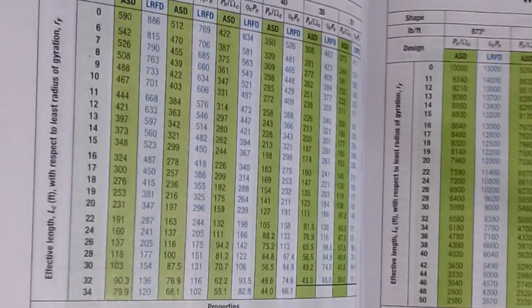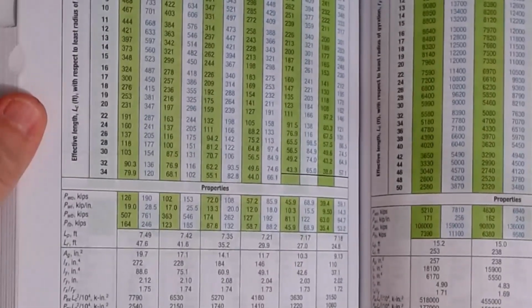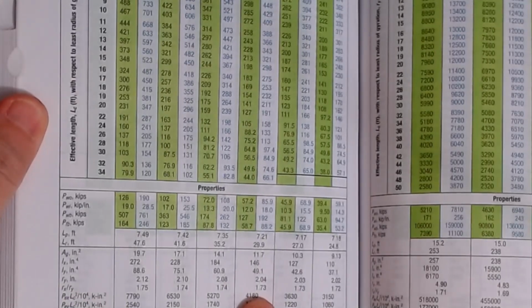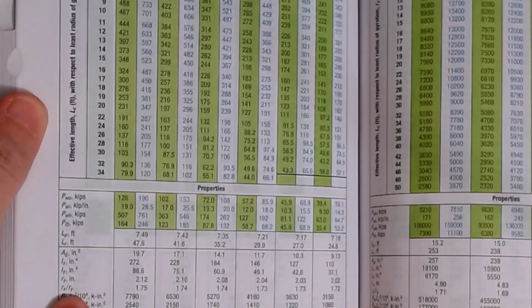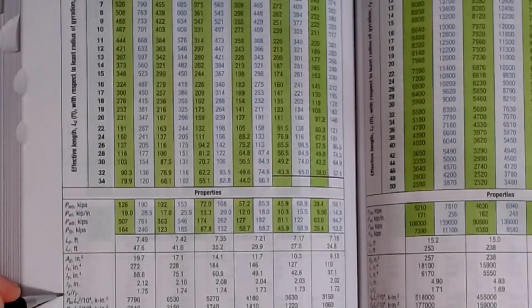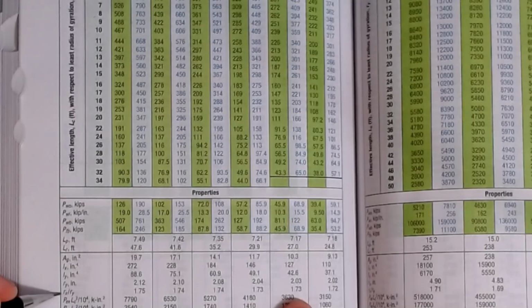You could either pull those values by hand, or at the bottom of these column tables, way down at the bottom, for my W8x40 it was this column, and for my W8x31, down here, there's an rx to ry ratio value right here, and that's the factor that you need. For a W8, we'd be looking at something like 1.73.